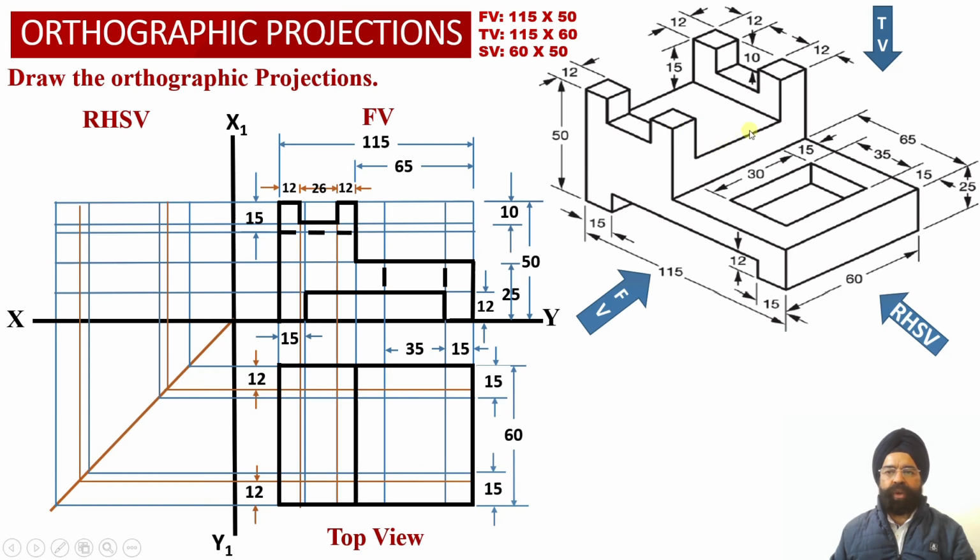So this boundary corresponding to web number 2, or the horizontal element number 2, will be visible to the observer. This way we can join the front face and the rear face at a distance of 65 millimeter from the right hand face, or at a distance of 50 millimeter from the left hand side face over here.